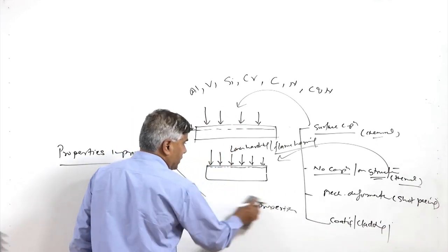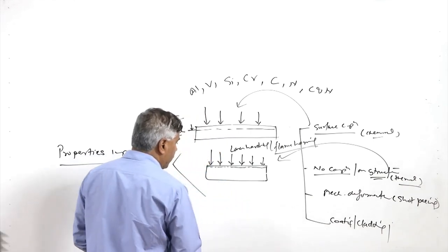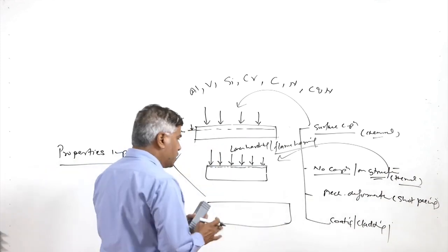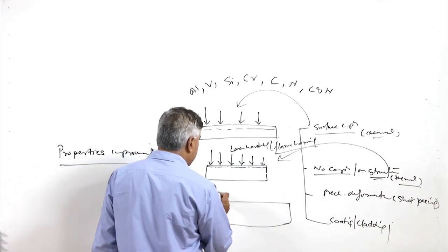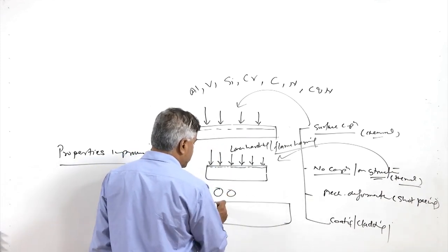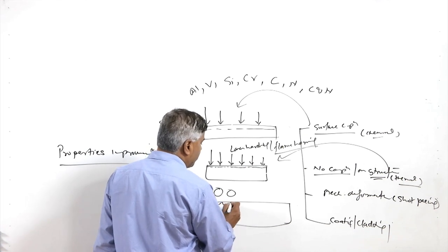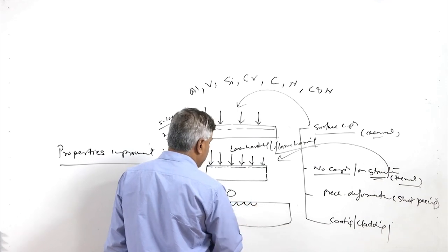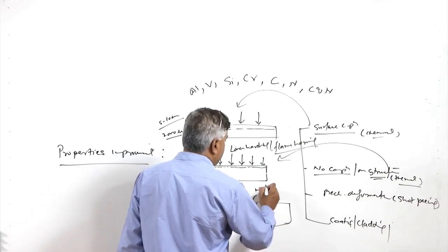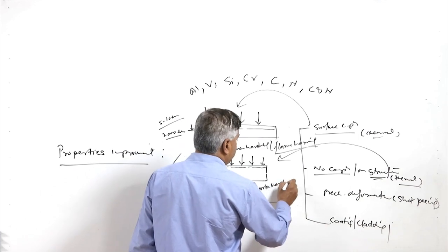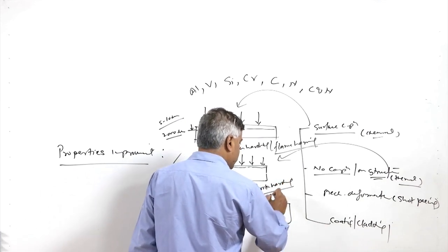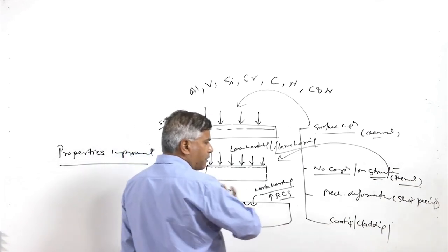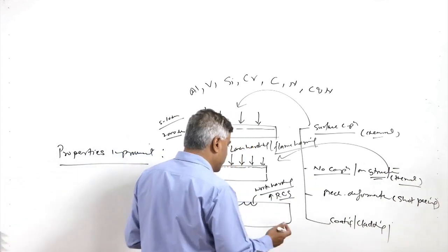The third approach is where deformation is applied. In this case, either controlled rolls or shot blasting is used. So, controlled near surface layer deformation is achieved, and this kind of deformation leads to work hardening or strain hardening of the surface layers, and also develops residual compressive stresses at the surface due to the near surface layer deformation in a very controlled way.